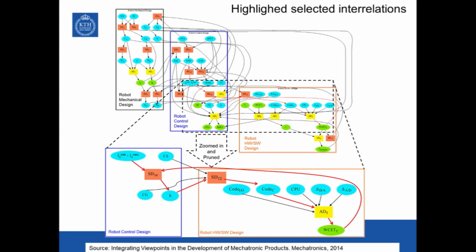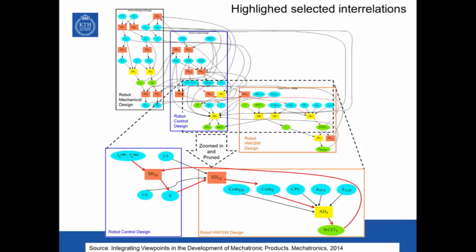So for example, as Herman mentioned, we need to choose sampling periods at some point in time. And they are typically chosen by the systems engineers or the control engineers. So there's a choice made here on the sampling period. The sampling period, as you know, will emerge in the software in terms of constants in our control algorithms. It will emerge as a constant using setting up a timer interrupt. So we will have a dependency in here.